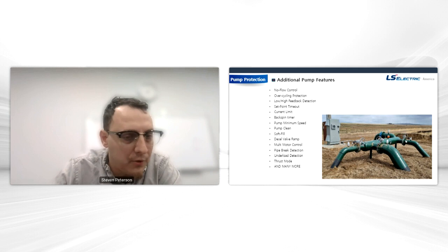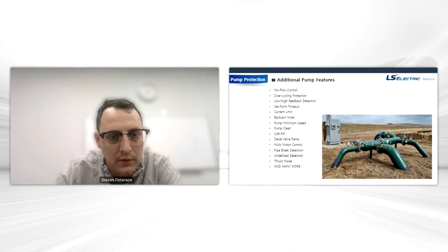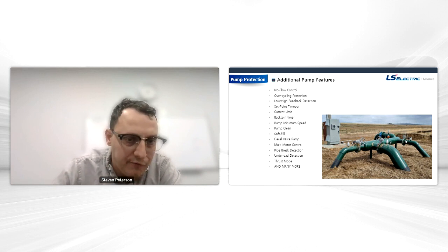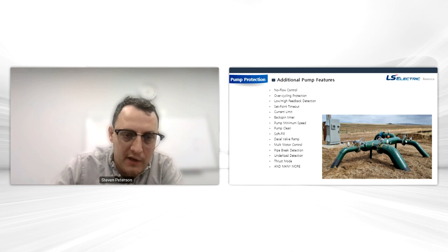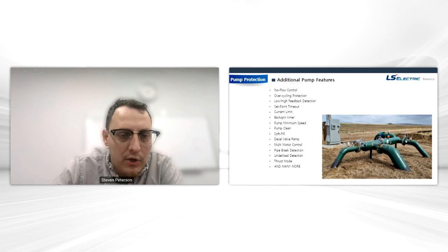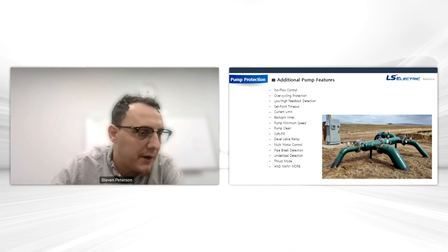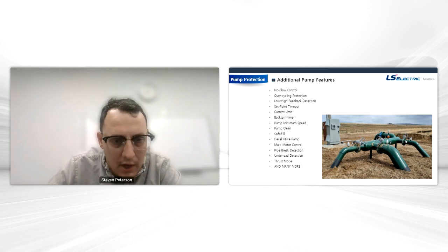Pump clean operation, common in wastewater where you're rotating back and forth, the anti-jam. We have a soft fill operation, decel valve ramp for check valves. That's a special decel time. The multiple motor control, so that's related to lead lag. We could also do it just with the digital outputs if you don't feel the need to run multiple drives. Pipe break detection, another one for irrigation. Underload detection, like you lose your prime going to the pump, your current drops, you could trip out on an underload detection trip. Thrust mode, great for you guys that are running submersible pumps, and there's actually more on top of that.